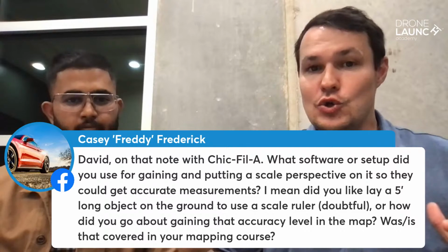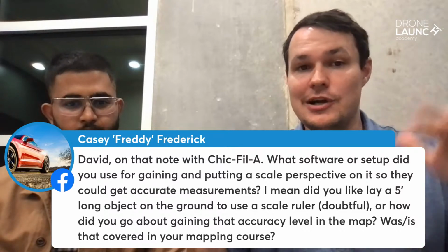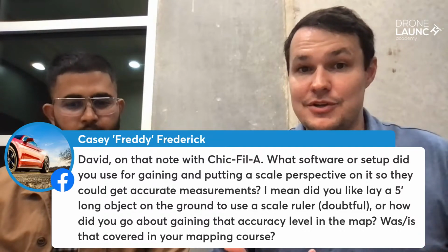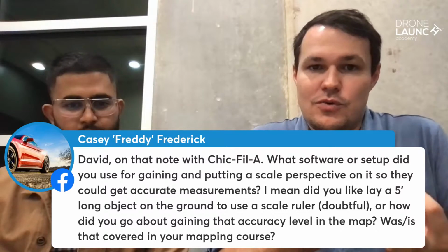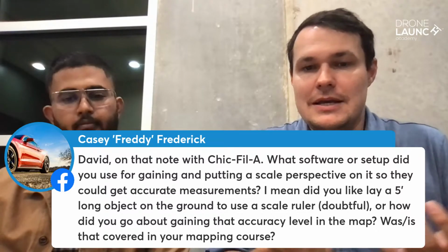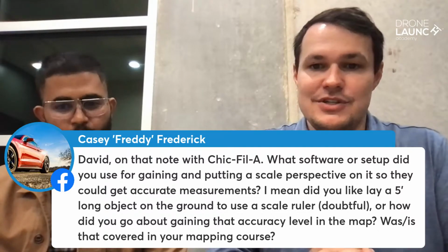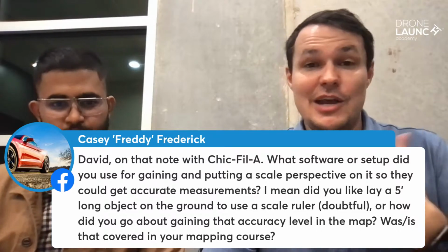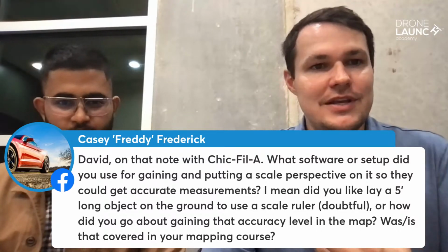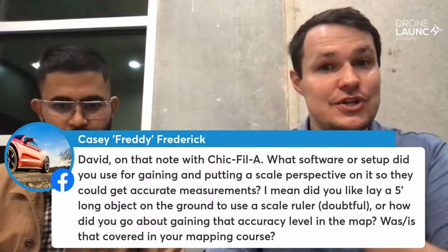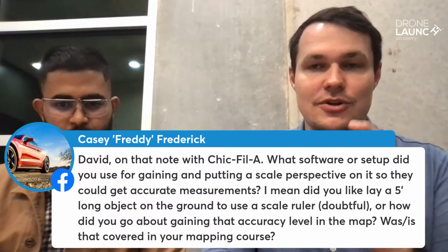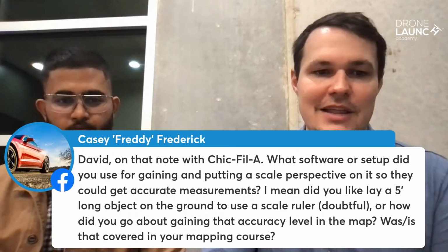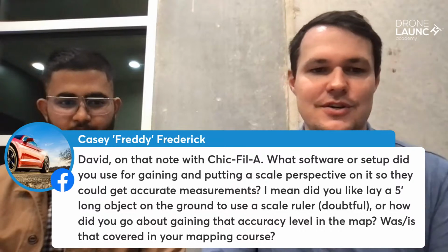Not to get too technical, but basically the lower you fly and the better camera you fly with, the better picture quality you have, and the more accurate and precise you can be, down to even just a few centimeters. So hope that answers your question. But yes, we do cover all that in the course, and we even talk about how accurate they need this to be, and how we can make sure we get that level of accuracy. We show you where to check that, and some of the math behind it. We don't get super mathy, but we show it to you in case you're really interested.